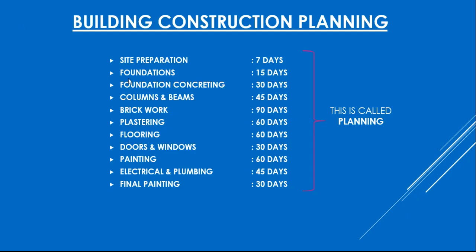Tasks means, what you are seeing here, these are all the tasks. Under each task, you will have subtasks. Foundations, 15 days, is the main task. Foundation means you can't simply get a foundation. What you have to do is the marking. Once the marking is done, you have to dig the foundations. And once it is done, you have to mark the center lines again. All these things are the subtasks.